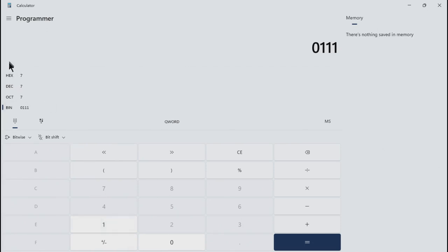A 3-bit number, the highest number you could store would be a 7. A 4-bit, you could store the number 15. If we go on up, 5, 6, 7, 8, 9, 10 bits, we could store a decimal 1023, or 1024 is how you'll see it, zero-based. It took 10 bits to get a number large enough to store the 1,000 points that we're dealing with.